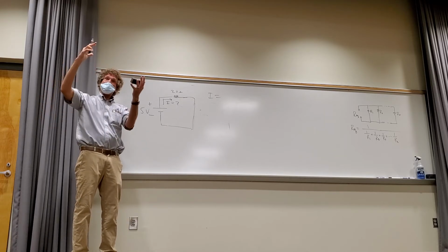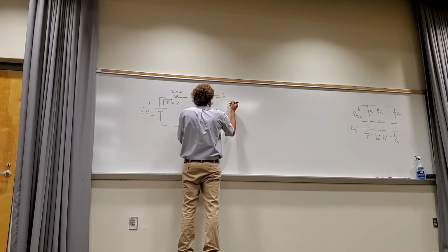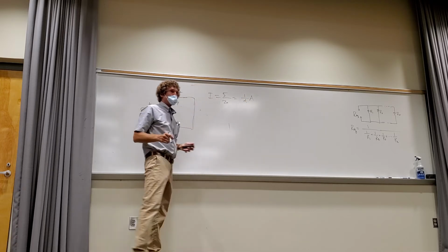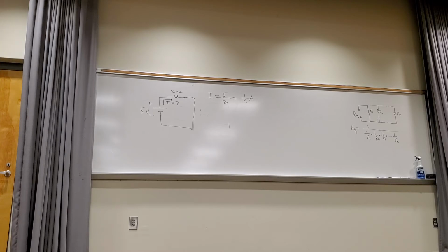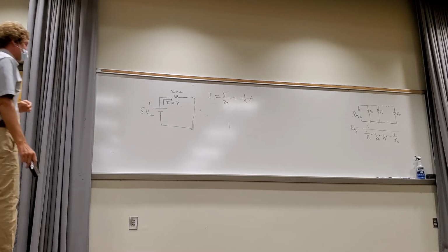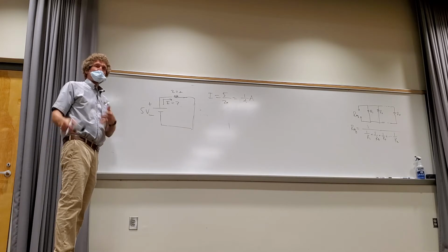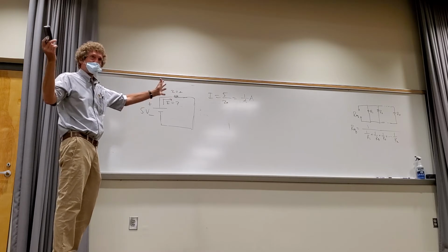1/4. It's always the pressure or the voltage, 5, right? Divided by the resistance, 20, or it's 1/4 of an amp. You all see that? How many see that right there? How many felt that that was a problem they could solve on their own? Give me a show of hands. I hope you all do, because that's right up your alley. It's very basic. This is something you get in high school. When I was in high school, I had electronics. I think when I was a sophomore, we had things like this, and they worked. And they would develop much more complicated stuff, but they would start right here to make sure everybody sees it.